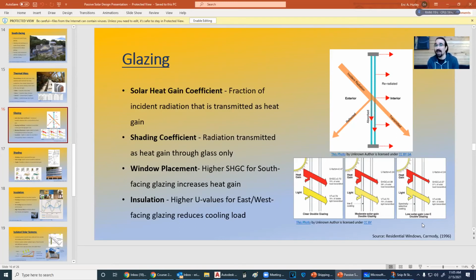You know, if you're relying only on solar heat gain, I could see where you might have a bone to pick about having to use low emissivity. But otherwise, because of the way that the house is going to use energy throughout the times of the day when it's not in direct sunlight, and when you don't want to have heating, especially in mixed humid climates, I think it's perfectly fine to continue to use low E windows in those situations. And if you want to have more heat gain in any one area, that can be done through sizing of the glazing and not necessarily the type of glazing that you're using.